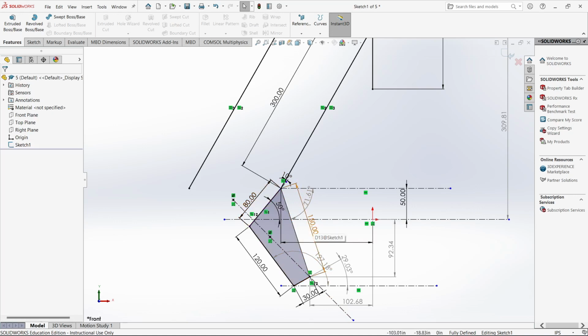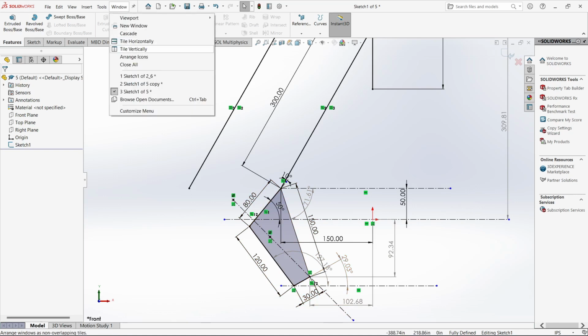This fixes two lengths, 80 millimeters and 150 mm, of this 4-bar mechanism, which should be a crank rocker mechanism so that it can be driven by a continuous motor at this particular length. Next, we have chosen this length to be 30 and 120. It should be such that it's a Grashof crank rocker mechanism. Here it can be seen that 150 plus 30 is indeed less than 120 plus 80, and also this length is smallest of all, so it's a crank rocker.